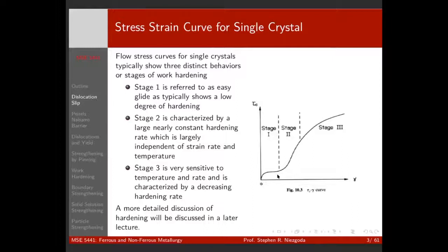So if we have that dislocation interaction, that's the key idea behind all of strengthening. Dislocations are the primary carrier for plasticity in a metal. There's also twins. Depending, you can have stress-induced martensitic transformations and things like that. But for the most part, we're really interested in dislocation motion.